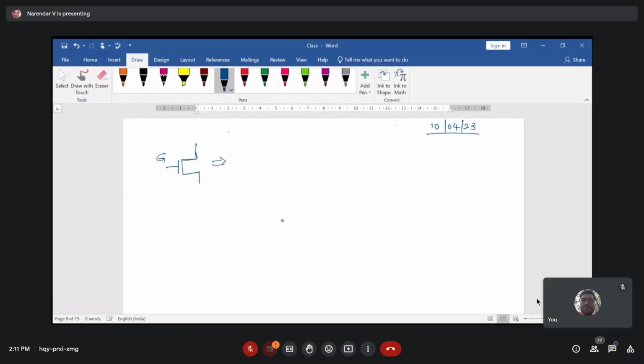So this is the MOS transistor that you see, and this is your drain terminal, and this is your source terminal. When you apply the gate voltage, if that gate voltage is DC, it creates a channel, and then you are going to have conduction in your transistor. And along with your DC source, if you apply an analog signal superimposed on the DC, then that analog signal gets amplified, and the transistor is supposed to be in the saturation region of operation, right?